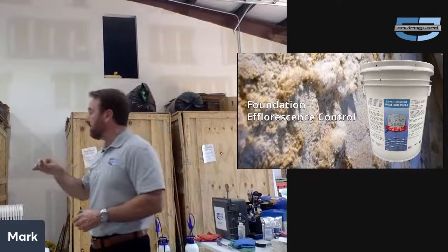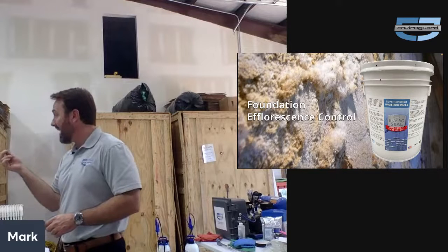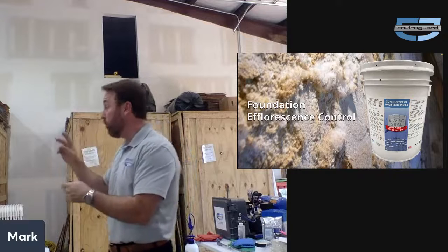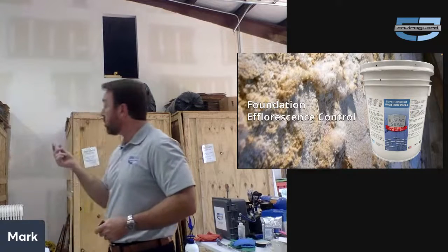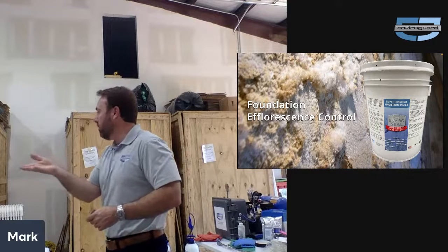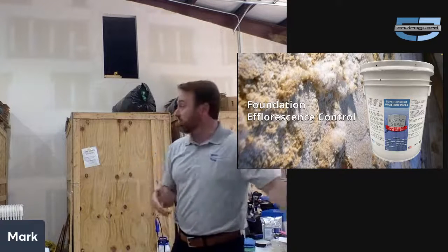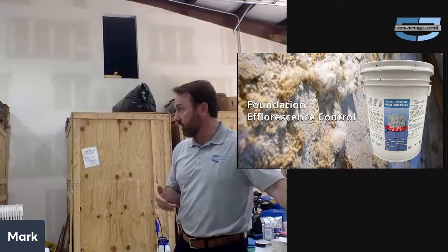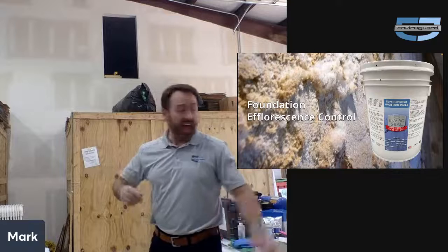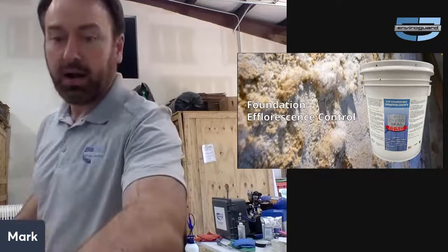Then that surface can be sealed, and what it does is it cross-links with that calcium hydroxide, and it becomes calcium silicate, okay? It just converts the molecule and bonds through a covalent bond, turns it into calcium silicate, and now water can't migrate to the surface anymore, okay? So it works as well as a densifier or redensifier for concrete, right, to shore up those voids that have filled over time from efflorescence, as it does to prevent it in general, okay? So that's our Enviroseal product.